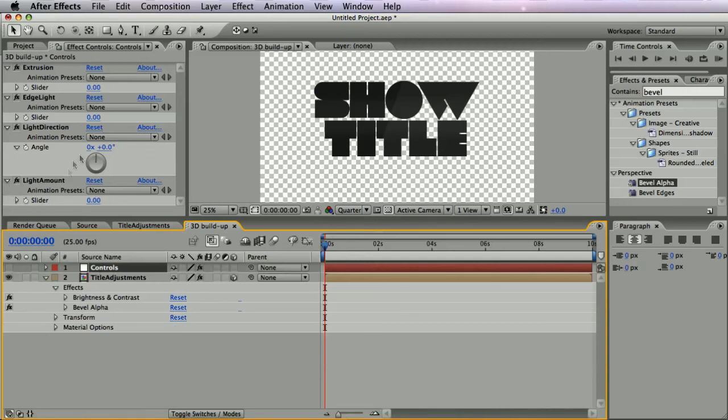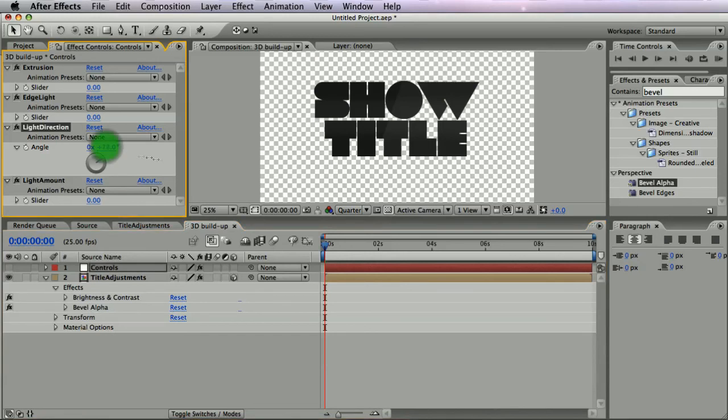At the moment, by this slider, you are actually controlling the bevel amount. By this angle control, you're controlling the bevel angle, and you can see it actually if you turn on the bevel amount, let's say 5 or even 9, you see a bevel, and now you can change the angle, and you see it moves around the edges.